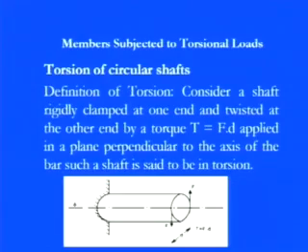So, you see along the longitudinal or along the hoop stresses, and that is what we were simply discussing. Even if it is rotating, only the hoop stresses are dominating, and these are coming due to this density times omega square r square. But if there is a shearing portion, that means if a couple or moment is acting on a particular area or direction, then what kind of stresses are there? So here we need to concern the torsional effect on a circular shaft.